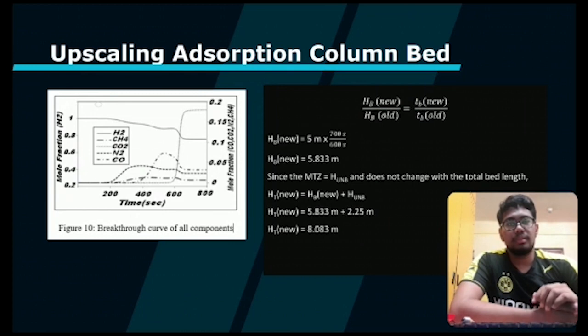Figure 10 shows the breakthrough curve of all components in this system. It can be seen that the mole fraction at time 600 seconds increased drastically since the unadsorbed solute is leaving the adsorption bed column. Therefore, the breakpoint, which is TB, of the system is 600 seconds.